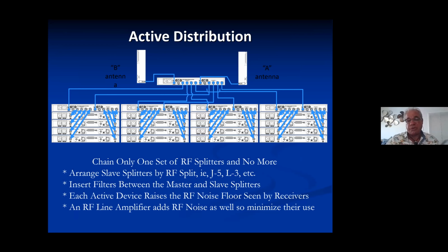We'll talk more about that next month. But essentially, your bottom end of your wireless mics, say, is 500 meg. Your top end is 610 meg. Might put a filter there for that. And then at the outputs of those, I'll feed another bank of combiners, but they will have a much more precise or a much more narrow band filter, again, to minimize the RF noise floor. Because every time you split and add active amplification, you add noise. So you want to keep that noise to the most narrow band possible.